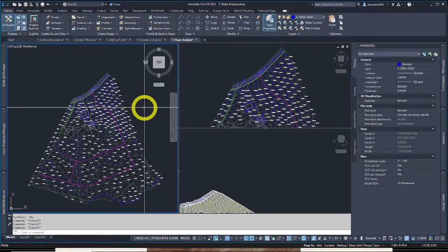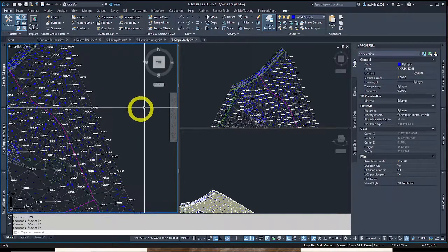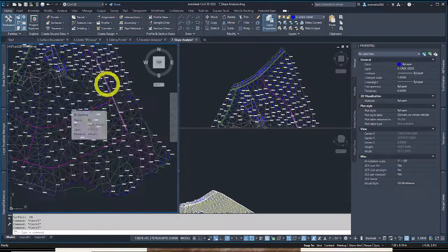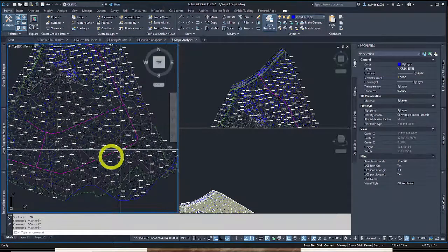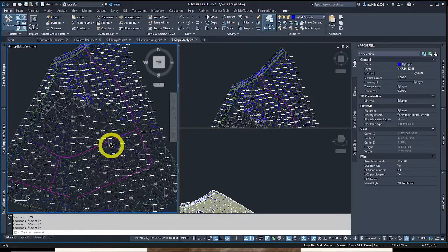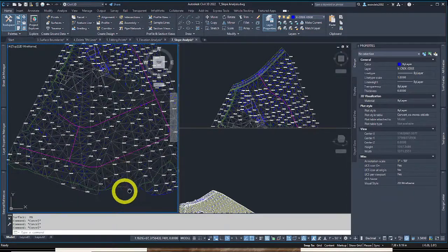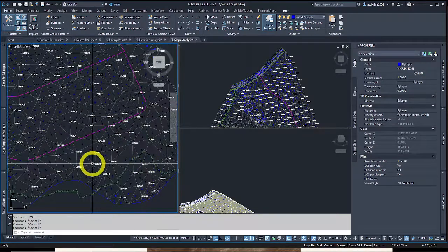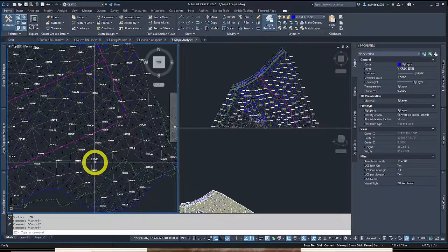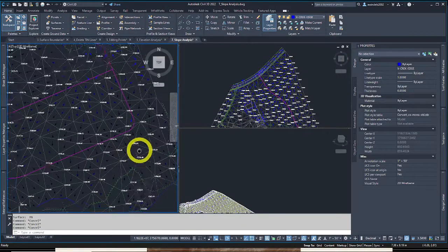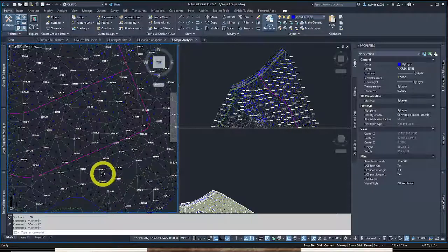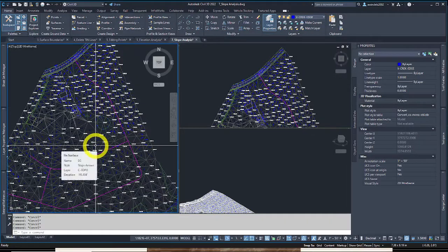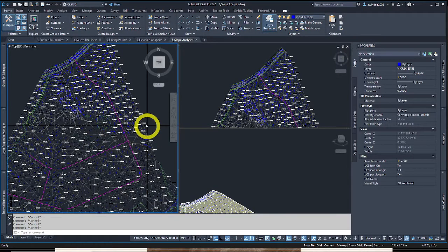It's going to show similar colors. Our tin is still gray, but it's going to show slope arrows. The different darkness reflects the steeper slope. So the darker the arrow, the steeper the slope. The closer to the light blue, the less the slope. So you can see quickly drainage analysis helps you see where the flow is going in the steepest areas. The steepest areas combined with what flow direction in general, showing you some patterns. So that's pretty cool analysis of existing ground surface and where and how to build and get some analysis on.